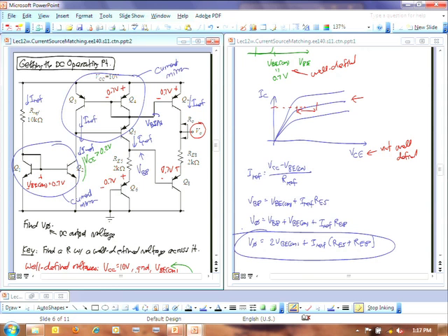Because, right, for a small signal at least, you got to calculate gm and r0. So that's just the nature of circuit design. You got to get those things. And soon it should become second nature to you, right? Soon you'll just remember, okay, 1 milliamp, then gm, that's just 1 over 26 or 1 over 25, right? Any questions about this? Any more questions?